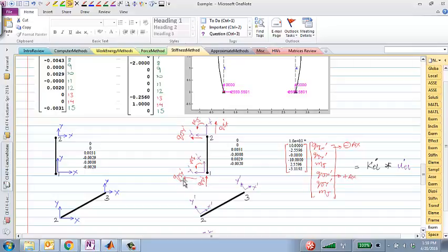And if I have a beam on the left end, shear force pointing up is positive, and for the corresponding section on the right end, shear force pointing down is positive, right? So indeed, Qiy prime is positive, Qjy prime is negative.